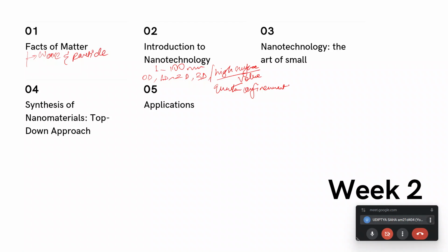So you learned a lot of methods: ball milling, liquid phase exfoliation, and laser ablation. Ball milling involves crushing bulk precursors using balls, usually made of tungsten carbide or stainless steel, in a vessel, and rotating them at high speeds. Then you have liquid phase exfoliation, in which bulk materials are broken down using ultrasonic waves.